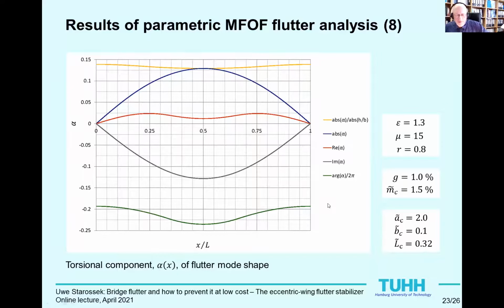This means that the phase shift of the torsional component relative to the vertical component is not constant, but varies along the bridge axis. These results support the earlier statement that with such a configuration, the vibration mode changes, and therefore it is more accurate to perform a multi-degree of freedom analysis instead of generalizing the system to just 2 degrees of freedom.